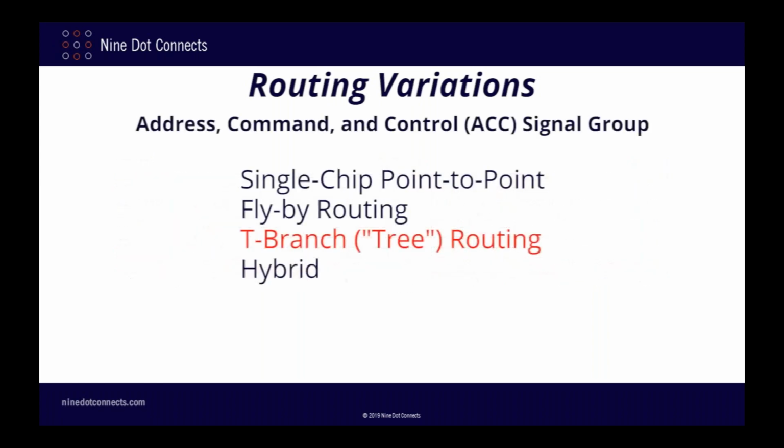Okay, now let's take a look at what is known as T-branch or tree routing. T-branch was the default routing paradigm for earlier versions of DDR, since previous controllers could not handle the time shifts caused by flyby routing. However, just because DDR3 supports flyby routing does not mean that you always have to use it. There is no reason why you couldn't use tree routing in a DDR3 design should that work out better for you.